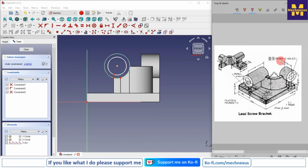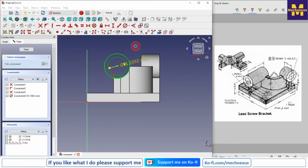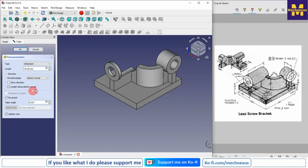So we can see here it is 2 holes, meaning the inside circle is the same for both. So I will select the diameter option 38.02. Now I move my dimensions, I close it, select the sketch and click on the pad and click on reverse, and it is 114. So give the value and say OK.